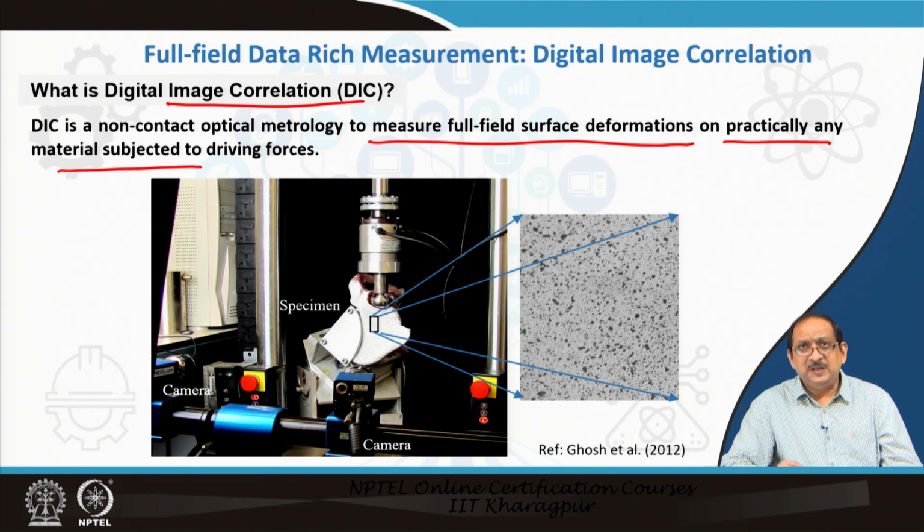Now, apart from the digital image correlation technique, in recent times another novel technique known as digital volume correlation has evolved for full field 3D strain and deformation measurements. The technique imports volume images of the component in reference and deformed states and is able to calculate the full 3D displacement and strain map.